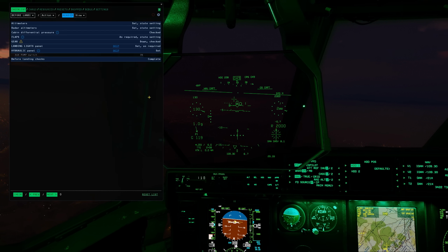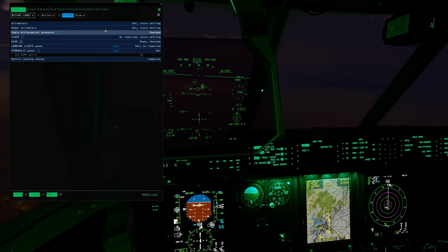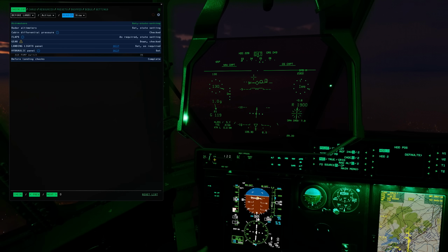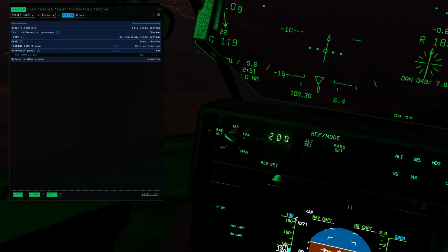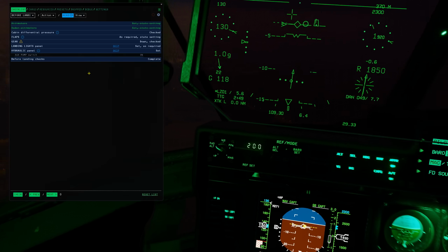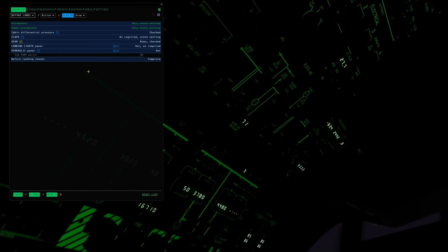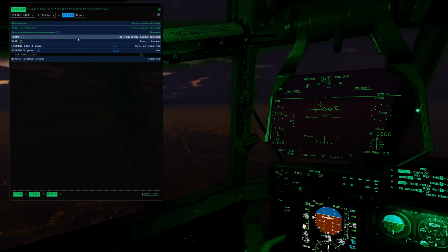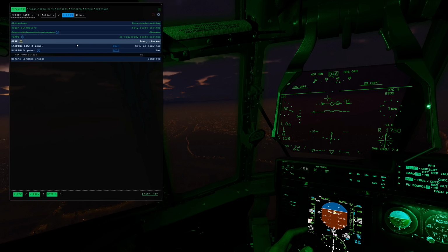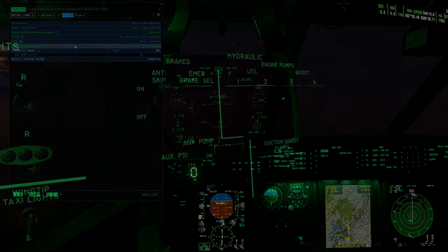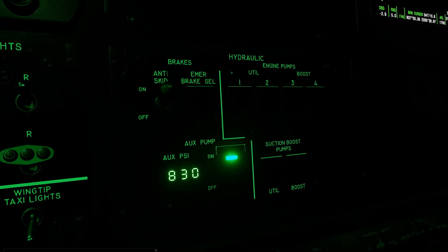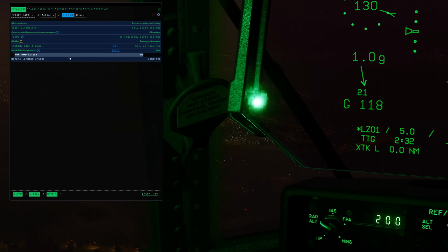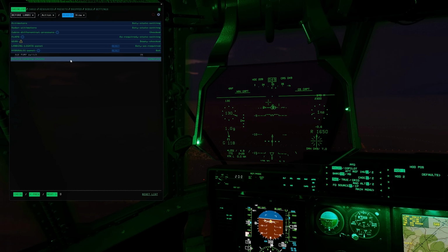Ready on the checklist. Altimeter. Barometric set to 29.33. Radar altimeters. Radar set to 200. Cabin differential pressure. Checked 0. Flaps and gear and lights. Full down set. Hydraulic panel. Set. And before landing checklist complete.